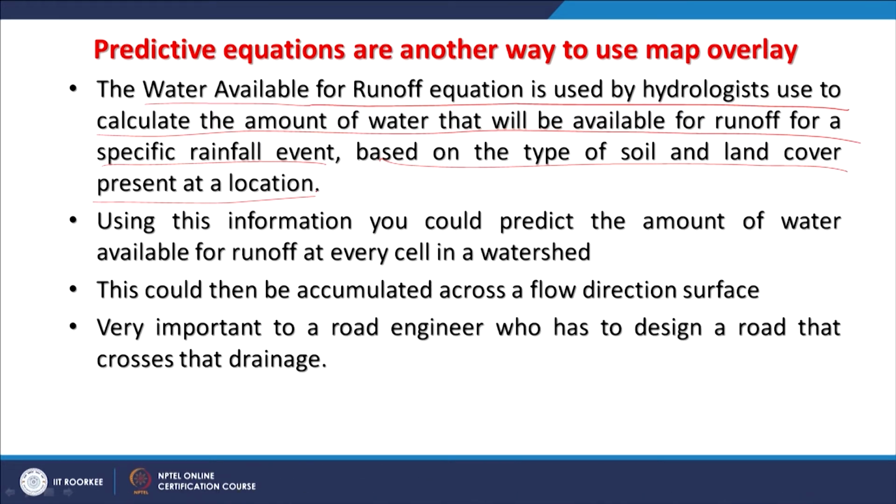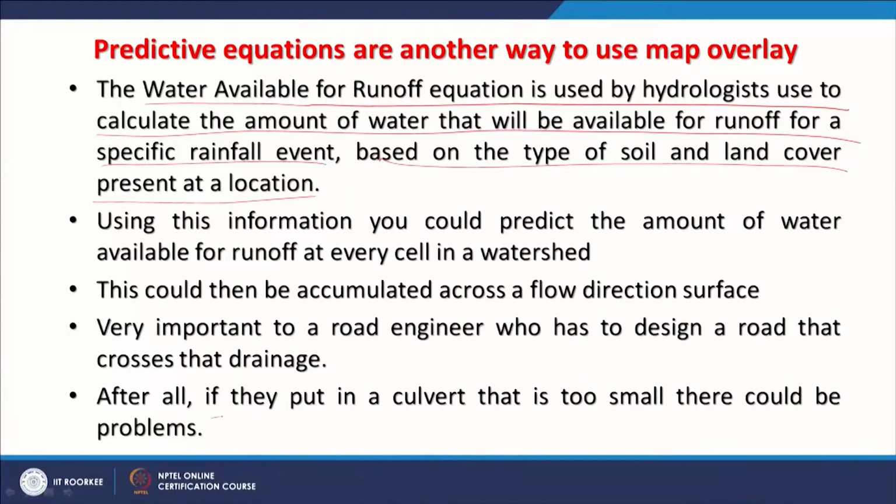And this is very important to the road engineers who have to design a road that crosses that drainage, because in flood events minimum damage or no damage should occur. Therefore, while designing these things, either small bridges or a culvert or whatever, these things should be kept in mind. After all, if they put in a culvert that is too small, there could be a problem. So, if estimations have been done properly through surface hydrologic modeling, then a proper design of a culvert will come,